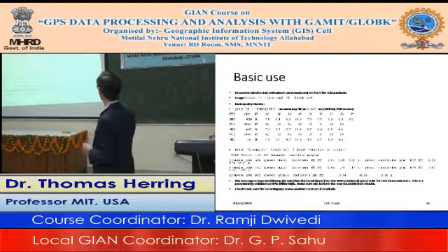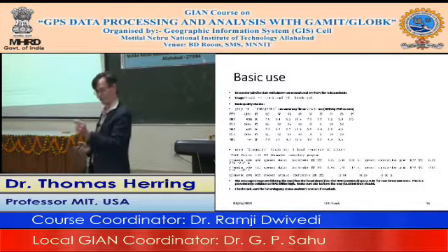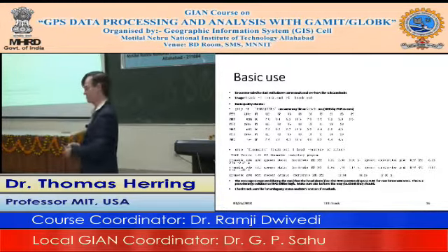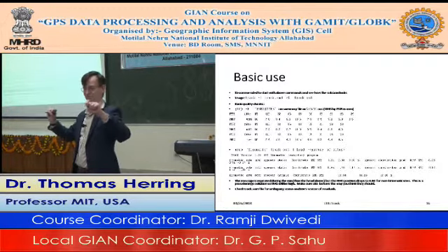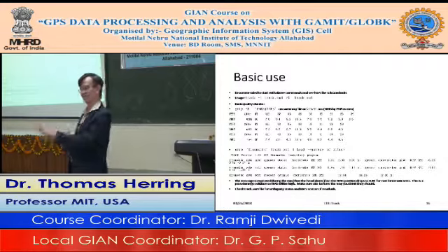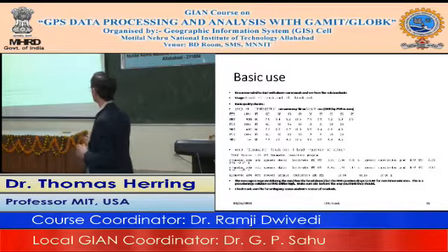The a priori coordinates tell you how far the site differs, and it appears to be static. This site also appears to be static, and this one called Rover has RMS scatters of 17 or 18 millimeters and appears to be dynamic. So the next thing you check is that your site that was actually moving does appear to be dynamic, and that any sites we're using as a base station, which are supposed to be fixed, actually appear static. And again, this looks really good.